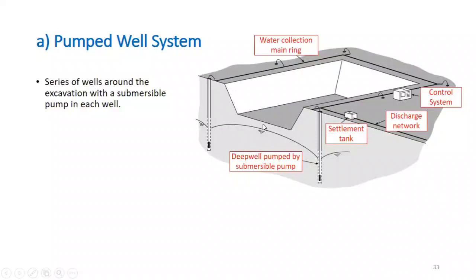So you have to bring the water table at least a few feet or a few meters below the lowest possible level of the excavation. You have to bring it somewhere here, the phreatic surface. In this case, what we normally do is install a series of wells along the periphery of the excavation. And these wells, like I said, are installed before the excavation begins itself.